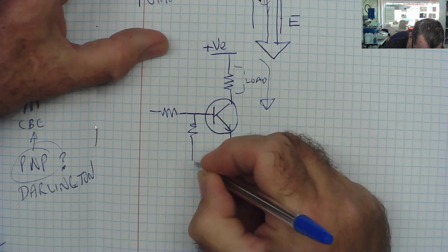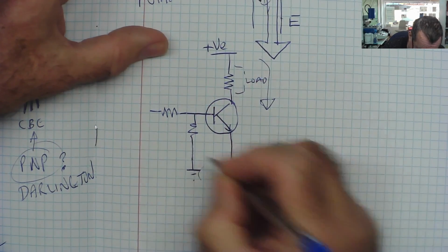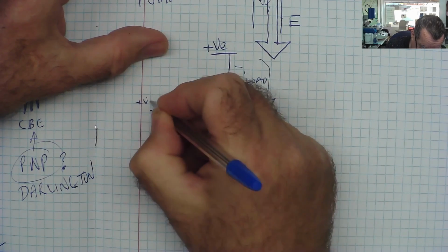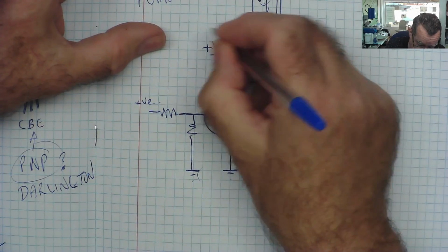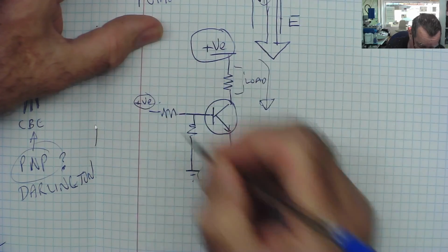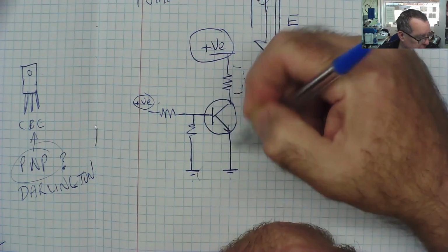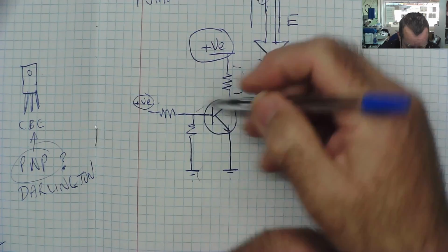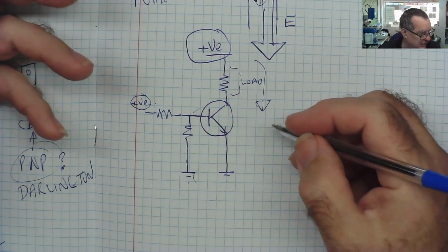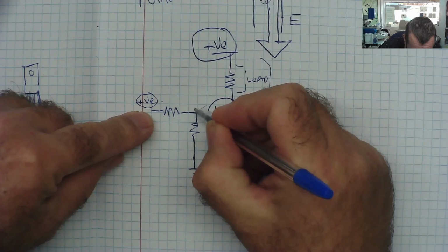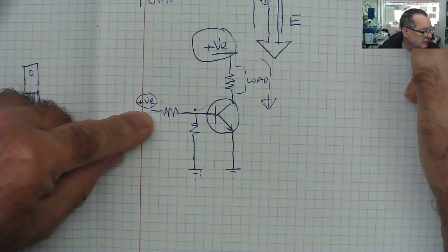So normally you have a setup something like this, and this has a small positive supply. Okay, this is the big positive supply, this is your small. With the semiconductor junction, that's from the base to emitter, we've just measured with our test meter, and it measures about 0.6 of a volt. So basically you have to apply 0.6 of a volt here before anything can happen at all.